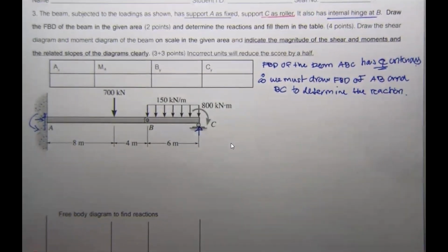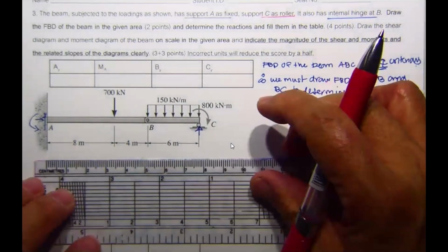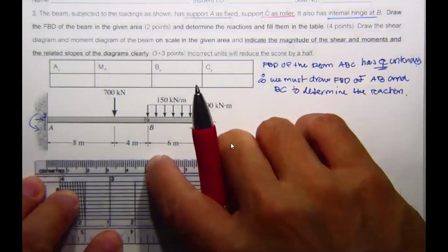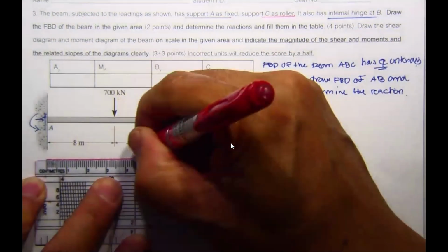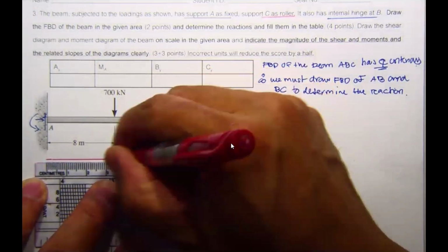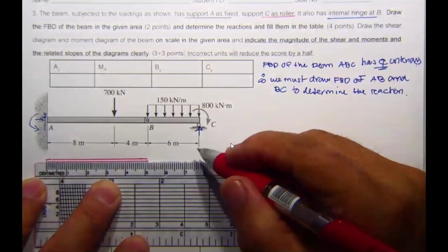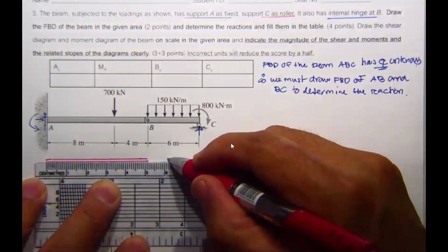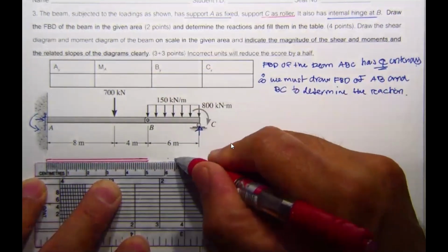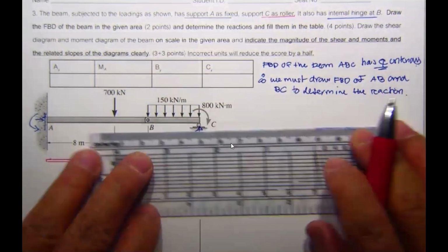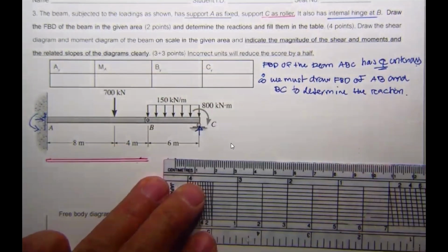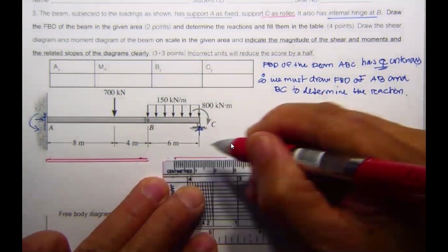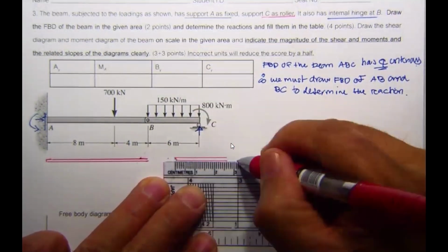Now, to draw it, you may follow what you have learned previously. Just make a copy of this one. The first one over here for AB. And then you may space it 1.5 centimeters and then measure this one 2.6. So you draw another portion of the beam.